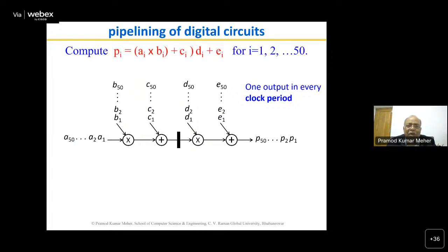So to do this computation, here this is a pipeline register, a parallel-out set of D flip-flops. If your data is 16-bit data, then you will have 16 D flip-flops to make a register like this. Put it here. Once this multiplication and these additions are over, suppose the clock pulse goes high, the result will go to the other side. At that time, a new data will arrive here. So the result will be passed to the second pipeline stage, and the first stage can take new data.